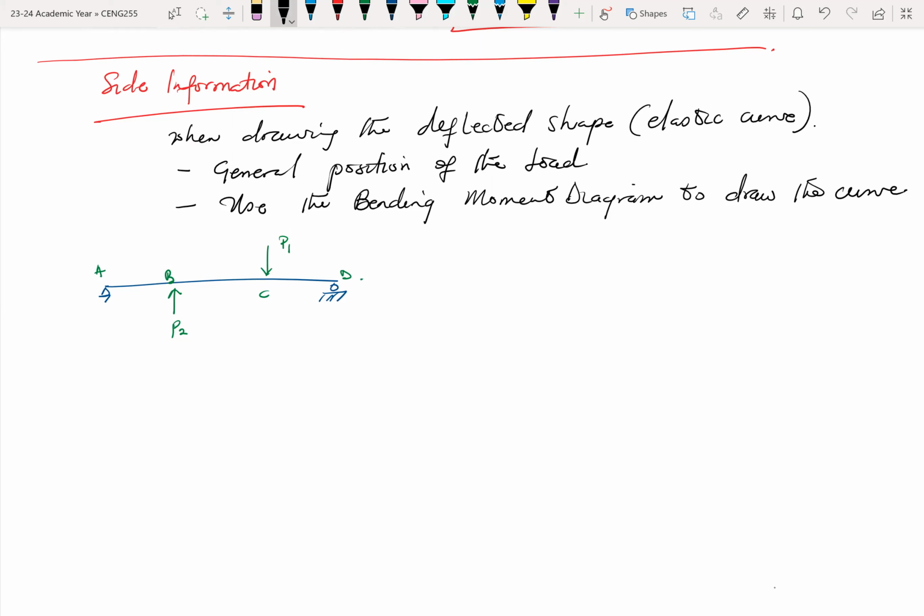Let me explain, in case you don't understand what the question is. If I have this as my beam, and this is P, the bending moment diagram can take this shape, where this is PL over 4. This is positive, or some books will do it this way.